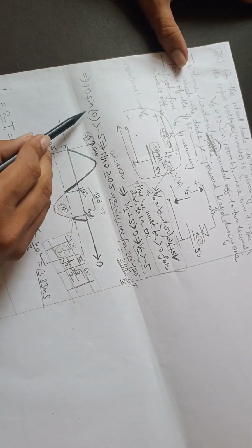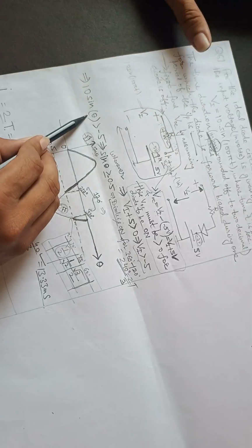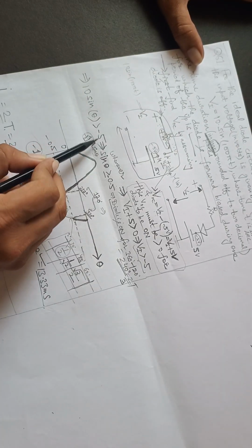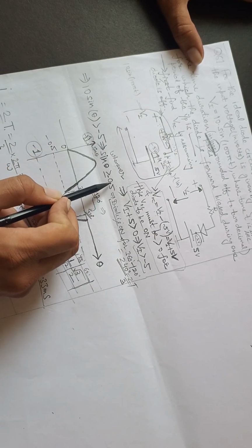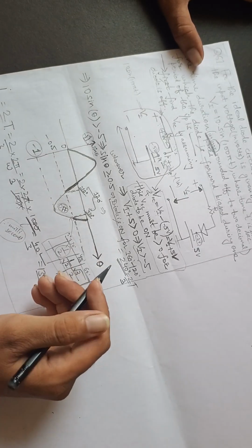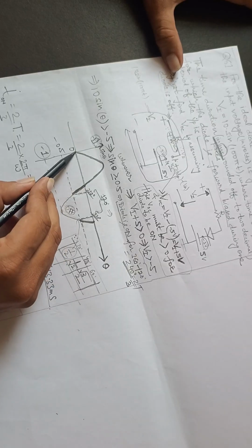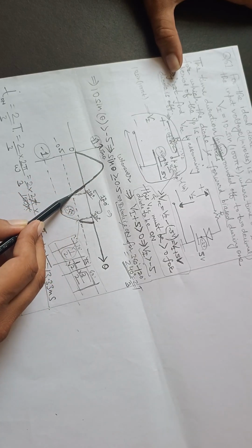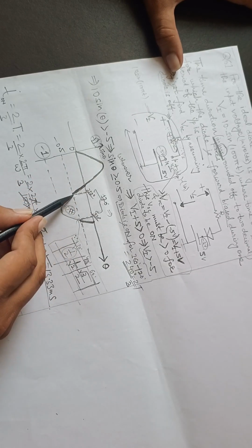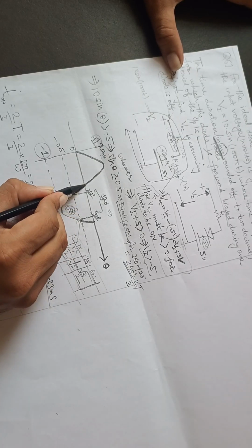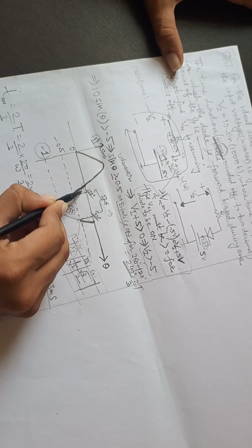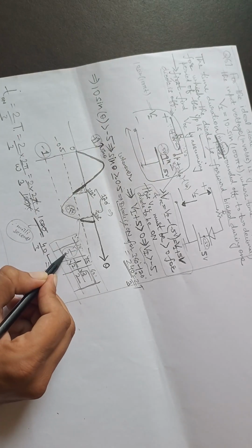Now what is VI? VI is basically 10 sin theta. It should be greater than minus 5, which means sin theta should be greater than minus 0.5. If you draw the sine curve, sin theta is greater than minus 0.5 up to this part. After 180 and then 30 degrees, if you move more, the sine curve crosses the value minus 1 by 2.